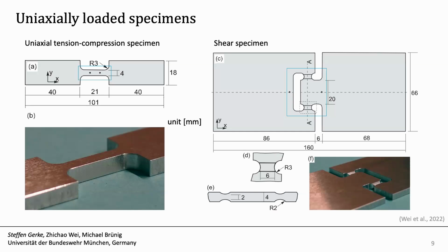Then we did shear experiments. We have this double notched shear specimen. I personally prefer two shear regions, because you can avoid rotations of these parts, and in numerical simulations you avoid problems with boundary conditions. Because if you have just one shear region, the parts rotate, and it doesn't matter really if you clamp it or if you just have a bolt there. These tend to rotate, so this is why we prefer these double notched parts. The idea is to have shear stresses in this region.